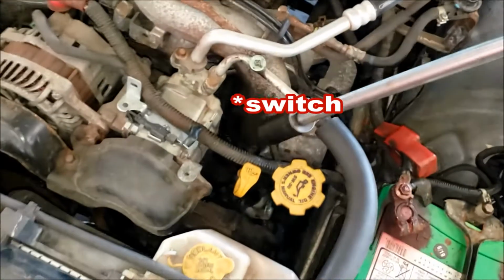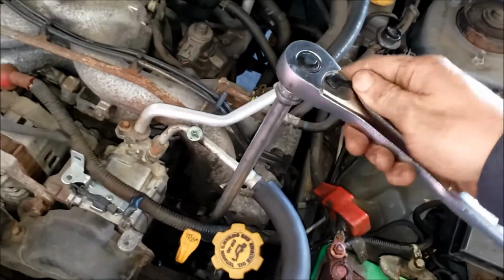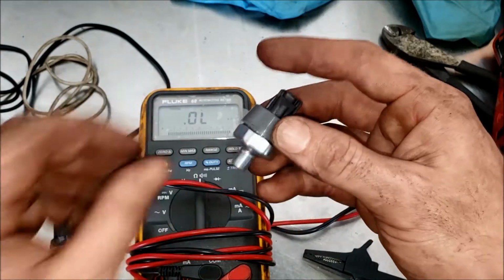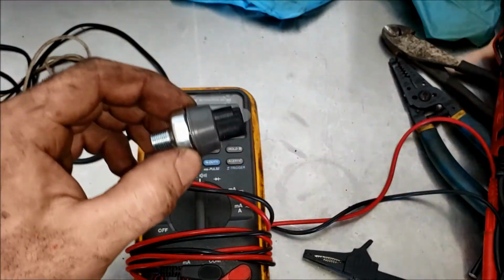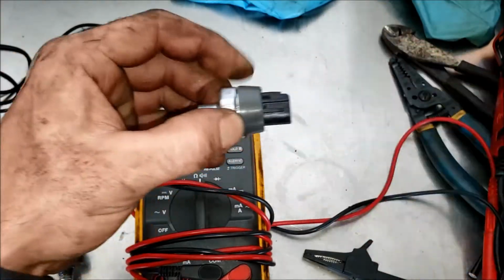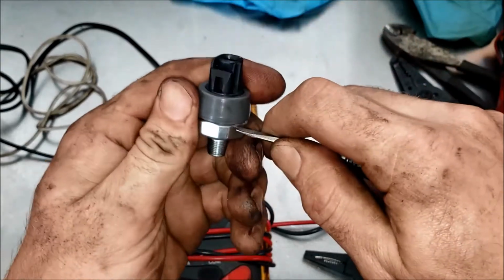I'll show you how to put that in. To get the sensor out, I'm using a 24mm socket on this long extension, and just lefty-loosey, pop that baby out of there. And here's my new switch, so let's test that real quick. One thing I just noticed off the rip here is that it has a sleeve that prevents you from putting the socket over top. So I guess we'll pop that off for installation, because I can't really get a wrench in there too easily.